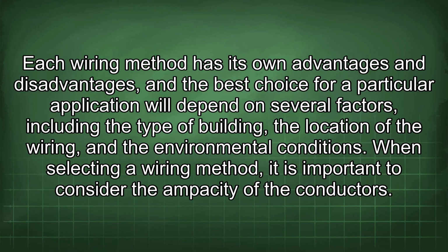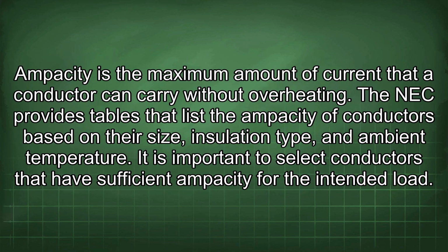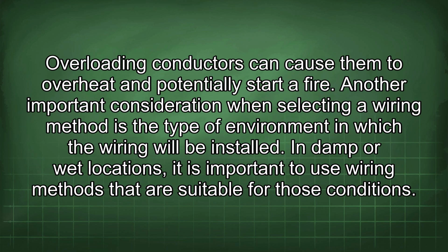When selecting a wiring method, it is important to consider the ampacity of the conductors. Ampacity is the maximum amount of current that a conductor can carry without overheating. The NEC provides tables that list the ampacity of conductors based on their size, insulation type, and ambient temperature. It is important to select conductors that have sufficient ampacity for the intended load. Overloading conductors can cause them to overheat and potentially start a fire.